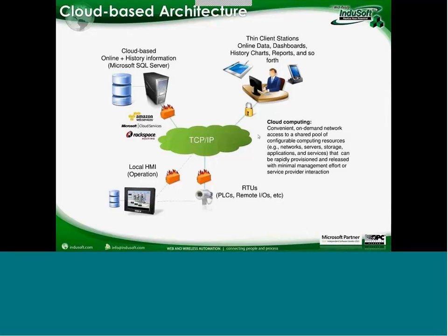So they have a local HMI on each one of the RTUs, but they also have a cloud-based system, a cloud-based server running in the InduSoft Web Studio on the cloud, receiving information from all the RTUs. In the illustration, I just have one, but they have several. Saving data, consolidating the data from all the RTUs in a single database, and InduSoft Web Studio is working as a portal for remote thin clients.